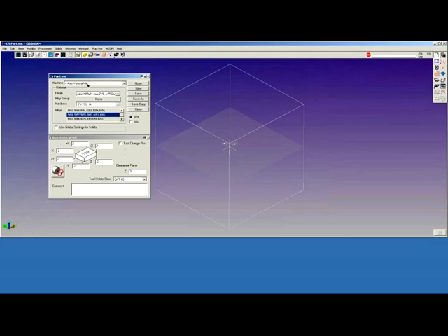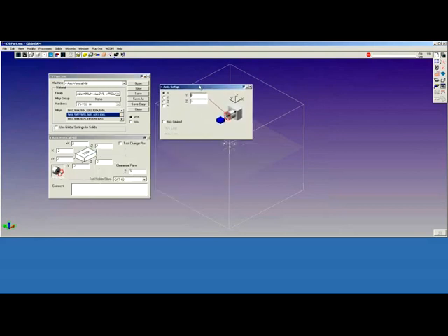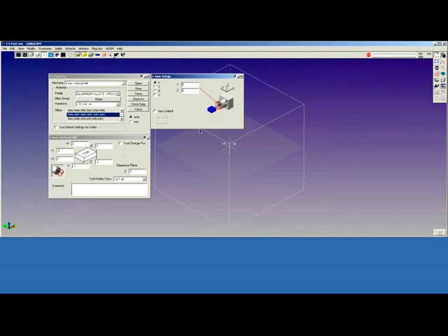When you select a 4-axis vertical mill, you get an additional icon on the lower left of the stock definition window, and this icon is for rotary axis setup. Click this tile, and you can determine how your part is positioned on the machine. In this case, I'm using a 4th axis mounted on the operator's right as he stands in front of the machine, and this can be toggled to the left side by clicking on the plus checkbox, or unchecking it to put it on the operator's right.